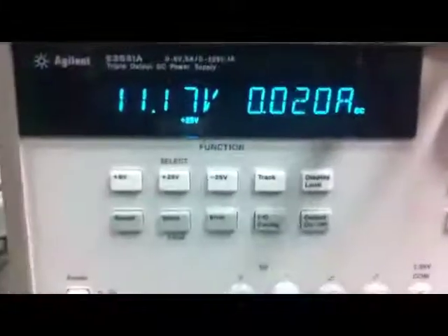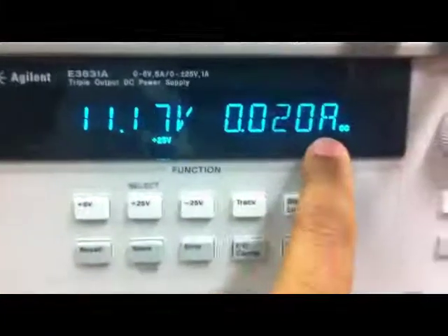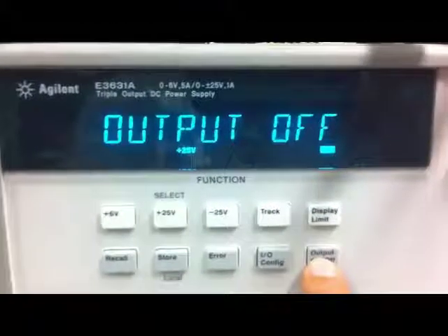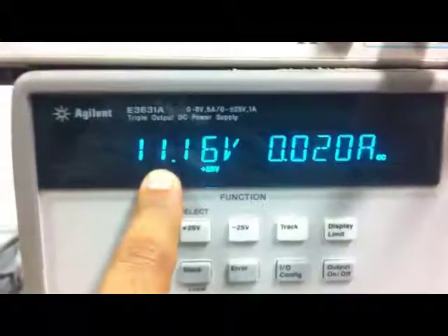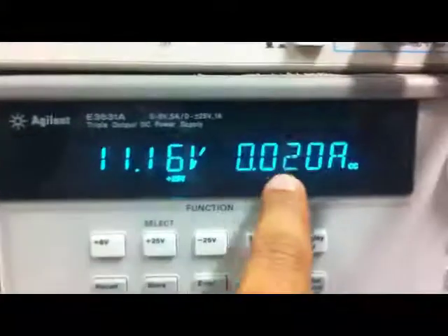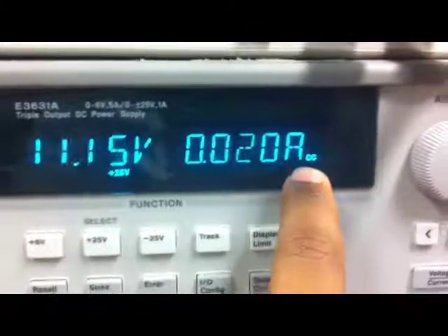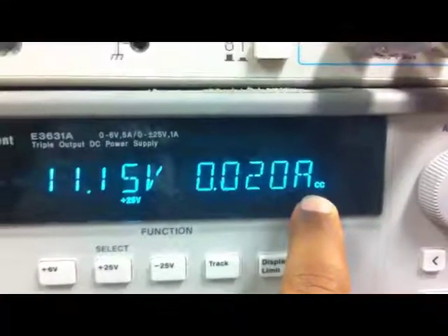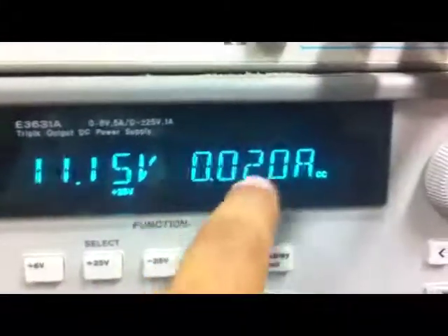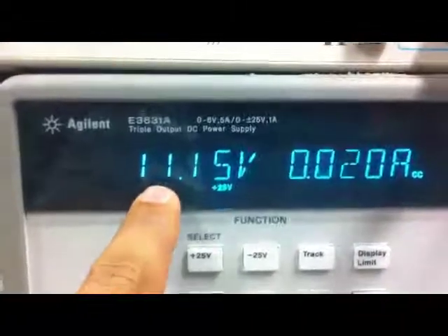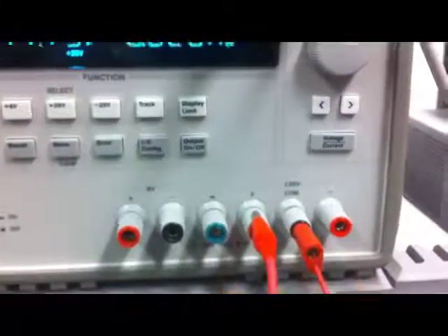So one thing you want to notice is that the power supply, let me turn the output back off, it's off. When you turn it back on, the voltage does not go up to 20 volts, because if the power supply has to output 20 volts, it's got to output more than 20 milliamps, but it's not possible. Notice, because of the current limit we set, notice how it says CC. So our power supply is actually now acting in constant current mode. So it's actually putting out 20 milliamps with a voltage of 11.15 volts across the output terminals.